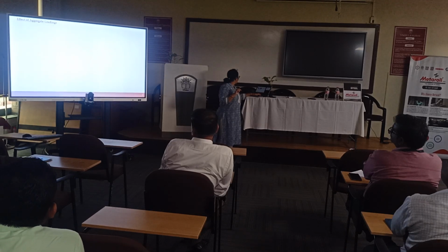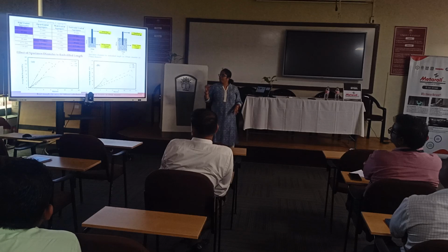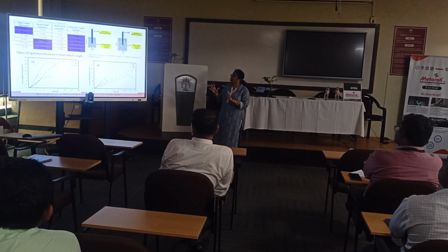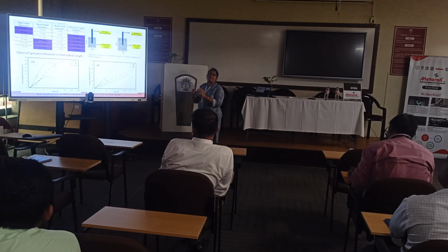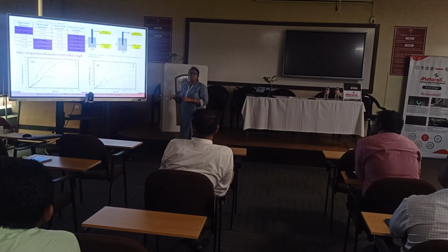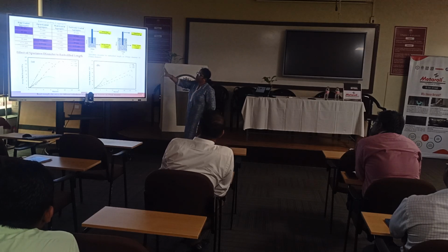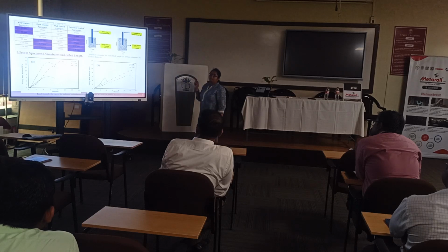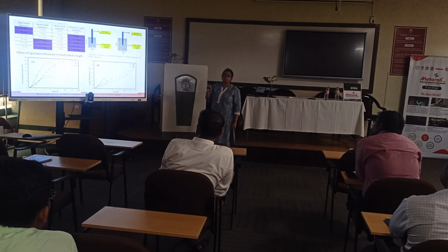Now I had a simple thought here: how do we do an aggregate impact? We do kind of aggregate variations. What is the effect of aggregate packing density on the overall question? Ultimately, concrete has crushed aggregates as its maximum volume, right? 60 to 80% of the volume is aggregates. When they are not properly compacted, what usually happens? It has more gaps, voids and pores.